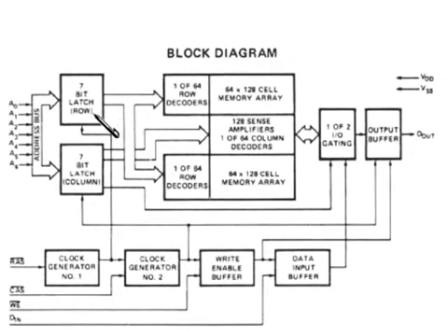So with 7 bits' worth of row addresses, that'll give us 128 rows by 128 columns. You multiply those two numbers together and you get 16K. At each location is only a single bit. As we can see in this diagram, we have a single D out and a single D in.